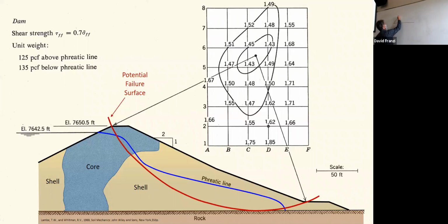That's solid rock there. And this is really, really coarse gravel, something that is very, very permeable in here. So if this is my core, here's the tailwater, the backwater. There will be a huge drop in head through that impermeable core material.